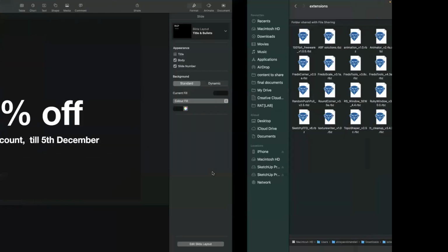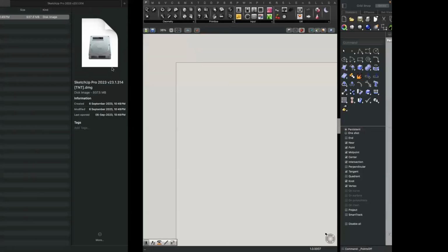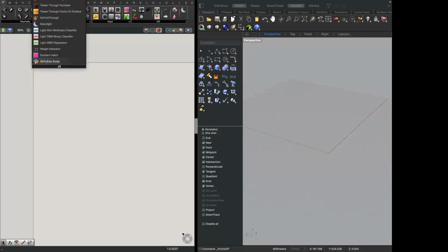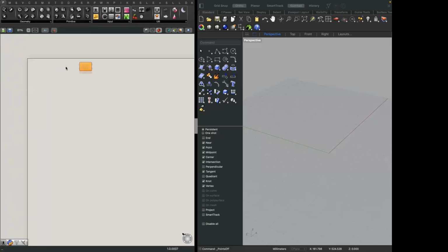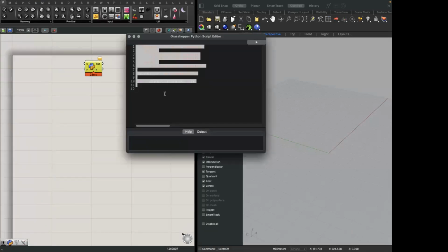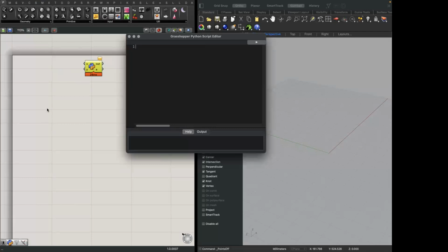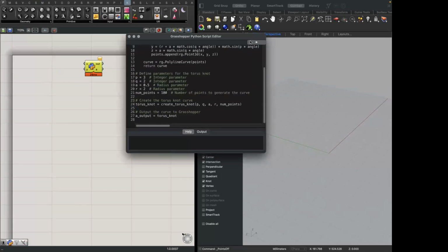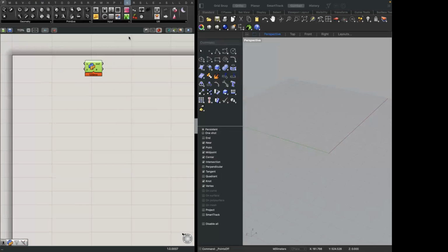I go back to the Grasshopper form, and then we have a component called GH Python. So I go here and just paste the script which we had copied and see if there are any errors in the script. Oh, the script is working right away.